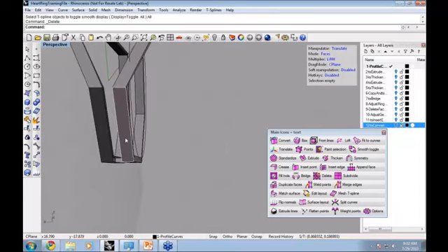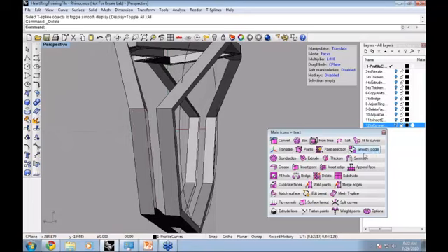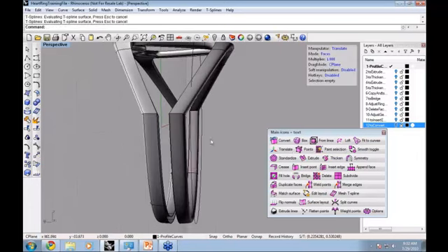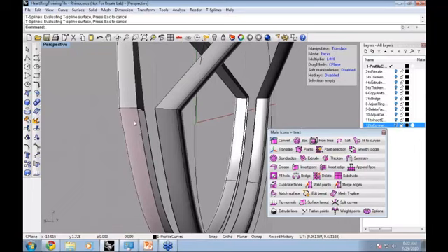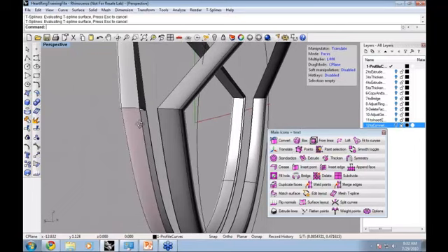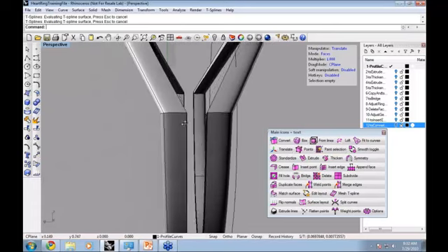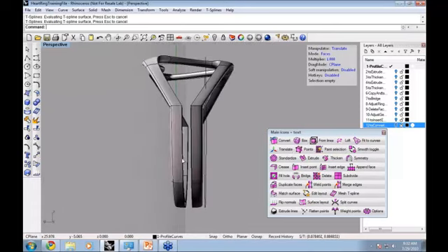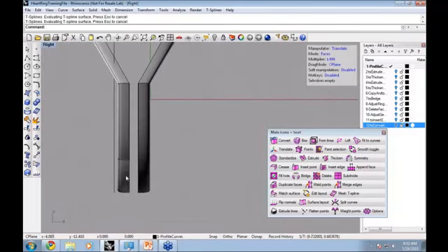So you can see there's a hole there. Let's go ahead and smooth toggle. You can see while I had those faces deleted, in this intermediate step, the surface looks like a zipper that's waiting to be zipped up or closed. So as soon as we merge this up, this will look a lot smoother. I'm just going to go ahead and move the faces a little bit closer together, just because I want there to be as little movement as possible when I actually do the merge.